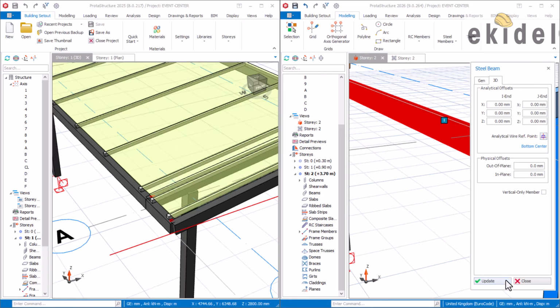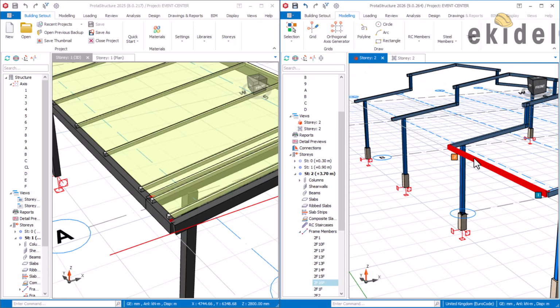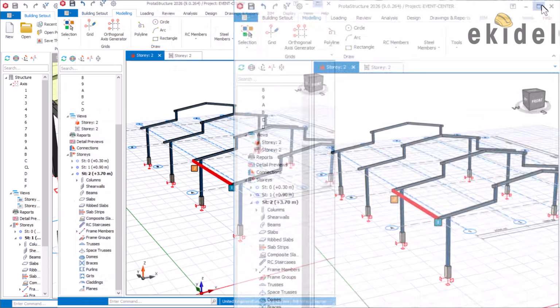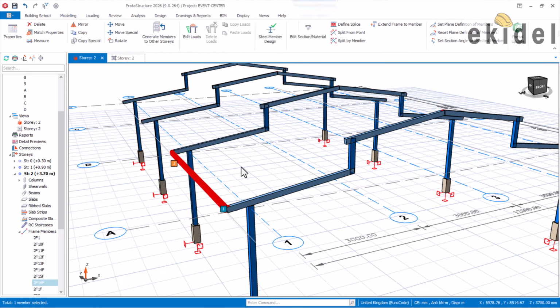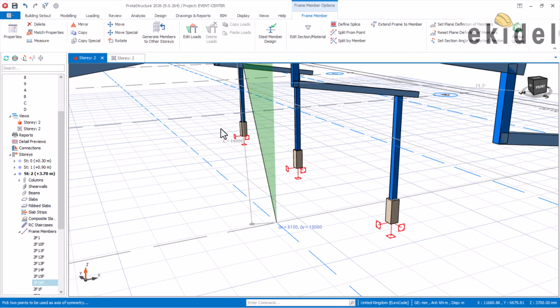Correct, and then click on update. That goes up now, which we have here. So once you've done this, I will maximize here, or I can still work there, then come here, click on this one, and mirror it from here, all the way from our grid line three, from this point of millimeter to this other point here.